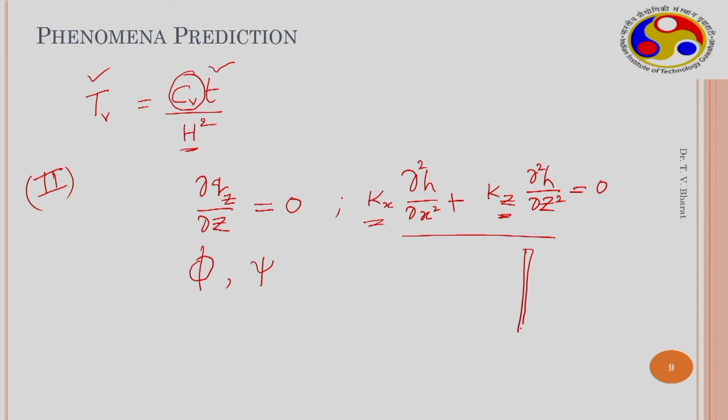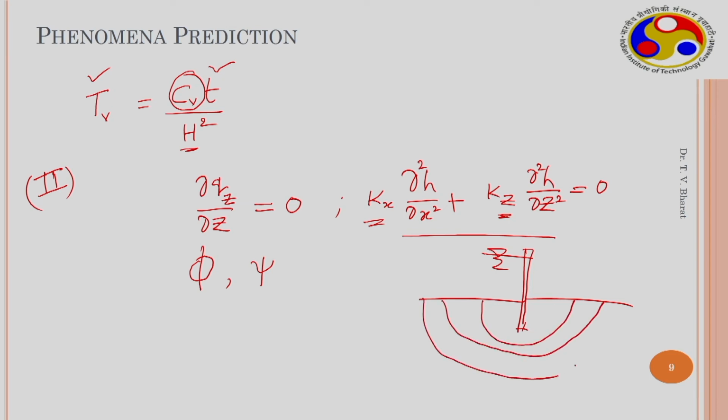If you have a dam or sheet pile wall, with the water behind the sheet pile wall, the flow that is taking place can be estimated in a confined environment very easily. Graphically we can estimate, and this one we have already learnt in basic soil mechanics. So here also we utilized the mass conservation principle. So there is a physical law, and the head here is the state variable. All the governing equations are always represented in terms of state variables.